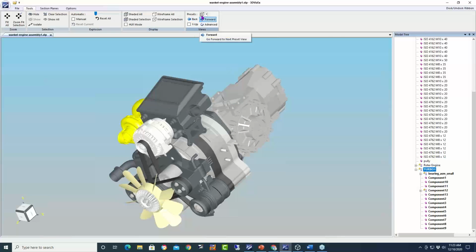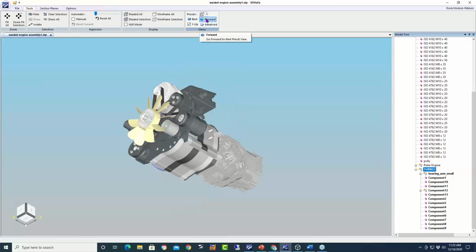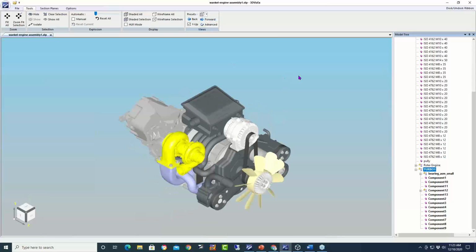So I mentioned things like isometric. So we have preset views. You could go to the initial view, so we could go back to where we started, or we could begin to look at perhaps isometric. We preset some isometric views because we believe obviously that's the primary projection now for illustrations. Isometric is certainly part of the standards and one you would definitely use as part of a spare parts catalogue, for instance. And so it's very easy to select those views using the software immediately.